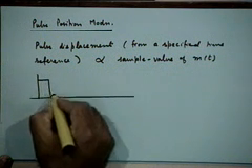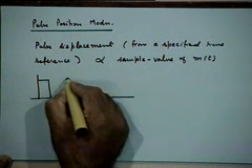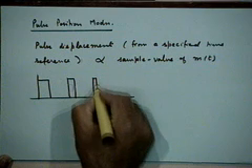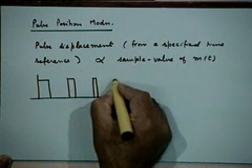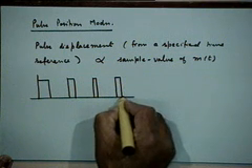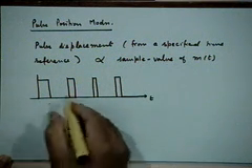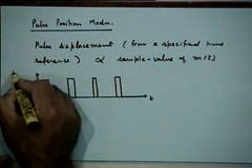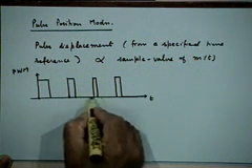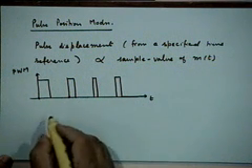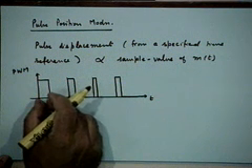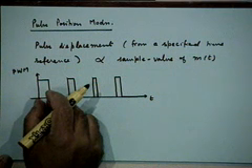Let's say this is your PWM waveform. I am just drawing some waveform arbitrarily. So this is PWM, right? This time interval is 1 by Fs, which is fixed. Now you want to generate a pulse. Remember, this width is proportional to the amplitude of the message.